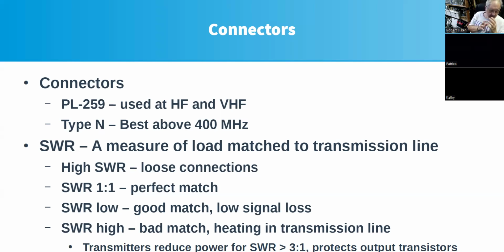And I have seen that because I had a not exactly a lightning strike, but I guess close enough that it triggered the gas discharge tube in one of my antenna switches, which caused it to be a short. And I was still able to send power into the antenna switch, even though it was way down to maybe 20 watts or so. Wasn't going anywhere.